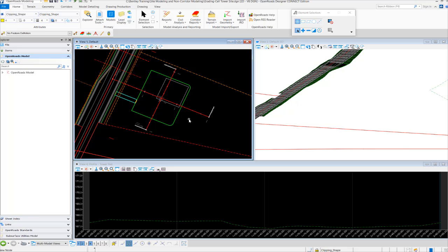So what we're going to do first is we need to assign elevation and create a profile for our tower pad. And then once we assign elevation and create a profile for our tower pad, we're going to project slopes out in all directions at like a -1% slope so that we can get the profile and elevation of the perimeter of our tower yard. So that's what we're going to do these next few steps here.